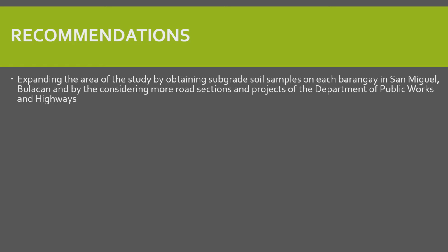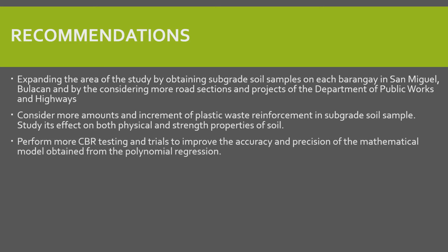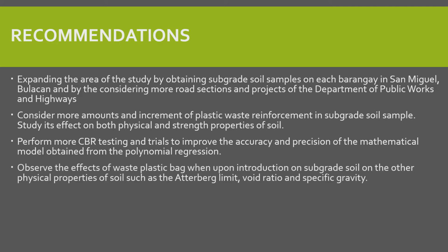For recommendation, expand the area of the study by obtaining soil subgrade samples from the different barangays in San Miguel, Bulacan. It is recommended to consider more amounts and increments of plastic waste reinforcement in soil subgrade samples. It is good to perform CBR testing and more trials to improve the accuracy and precision of the mathematical model obtained from the polynomial regression. It is highly recommended to observe the effect of plastic waste bag upon the addition on road subgrade soil of other physical properties such as Atterberg limit, void ratio, and specific gravity.